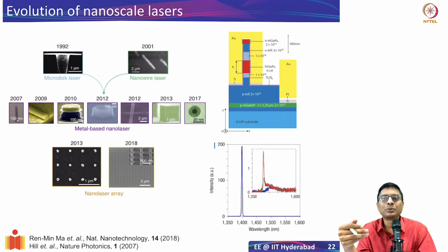So if you want to have a good working laser, we need to make sure that the Schottky barriers are avoided, or at least minimize the junction width, the Schottky barrier width, so that tunneling happens and we can overcome that. So in this case, that's why whenever you contact with metal, they try to have large doping so that the barrier is very, very small and narrow, and you can actually overcome that. And also the entire structure has to be very, very carefully designed so that you minimize the resistance for both electrons and holes. So a lot of careful design is done to do this.